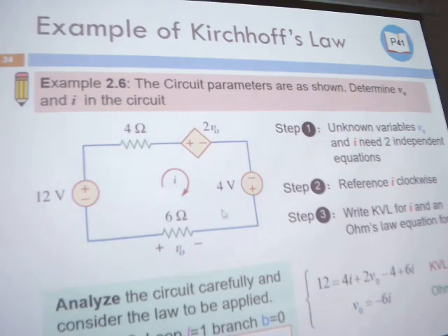Okay, so for the KVL equation here, choose this point and this point. Maybe we can put one over here and one over here. And we know that the voltage difference is 12. So it must equal the sum of the voltages here. Here it doesn't give me any reference direction for the resistance, so we can choose passive sign convention.